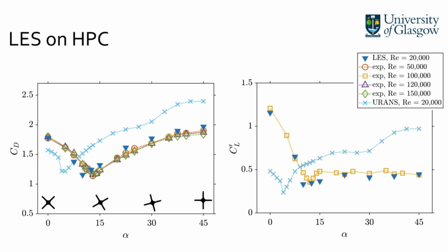So overall, the URANS approach provides useful insights into the key features of the flow past the succulent-inspired cylinder, but for close quantitative agreement to experimental data, we need the 3D eddy-resolving methods, such as large eddy simulations. And we can see that the results of our large eddy simulation show pretty good agreement with the